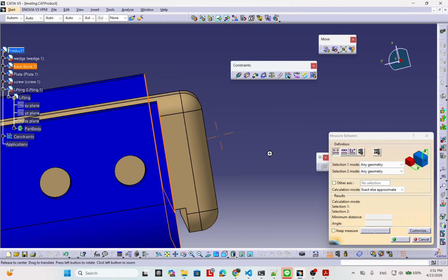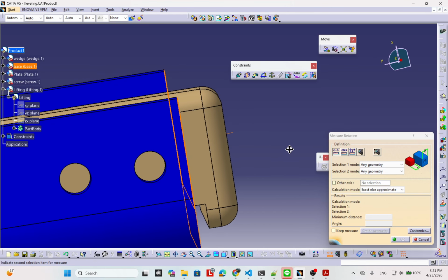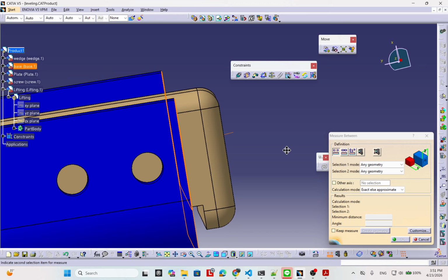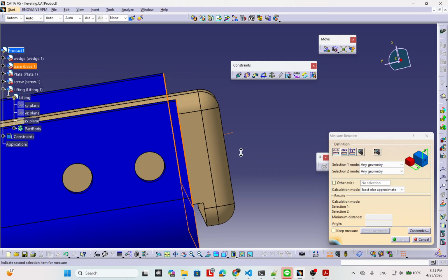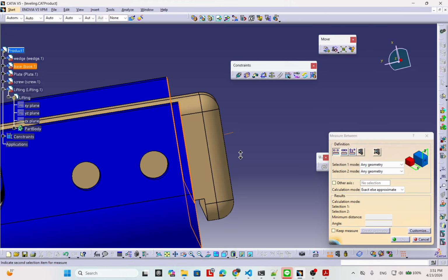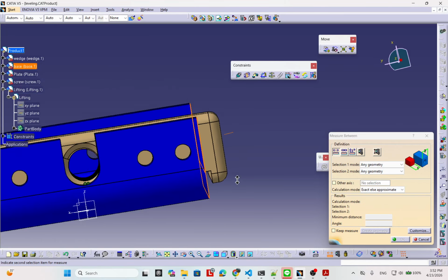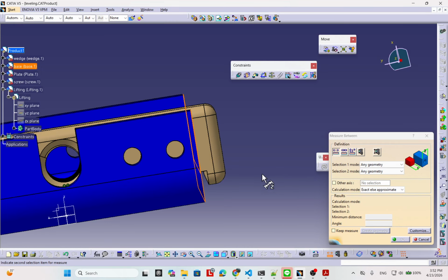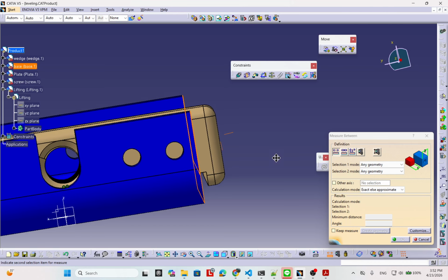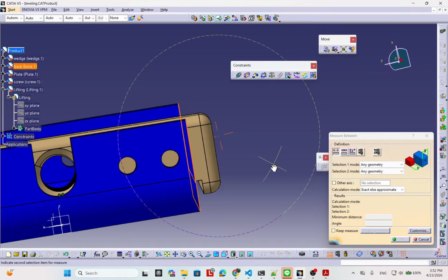If you hold the middle button and click the left button, then release the left button, the mouse pointer becomes an up and down arrow. Then you zoom by dragging your mouse on the mouse pad, zooming in and zooming out. The last technique controlled by your three mouse buttons is to hold the middle and left buttons.